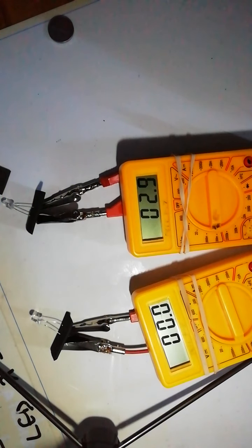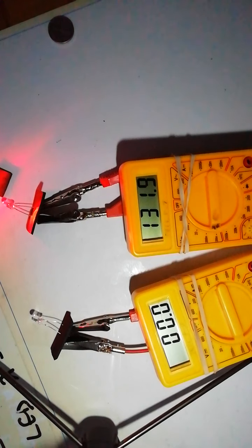What happens if I try with a red light-emitting diode? If I shine my red light-emitting diode at my red LED, you can see the reading is actually much, much greater. It's much more efficient. This silicon's much, much more efficient at absorbing those red photons. That junction has been created to be very effective. So I'm getting a reading of about 120 millivolts.